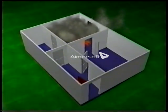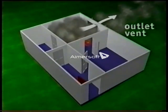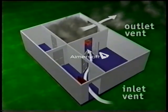When vertical ventilation is too difficult or too dangerous, horizontal ventilation will be the only alternative. Horizontal ventilation is the term for making use of doorways or windows in the fire compartment. And here also, it will always be most effective to have the outlet vent as high as possible and the inlet vent as low as possible.